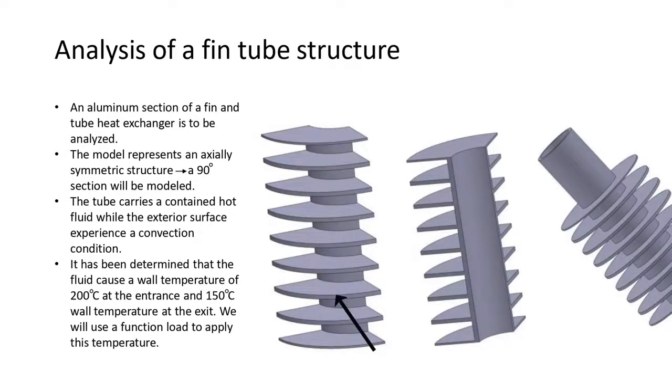So we need to apply a uniformly varying temperature load on the inner surface, and then we need to find out the temperature distribution throughout the fins using the convection mode of heat transfer inside Ansys Workbench.